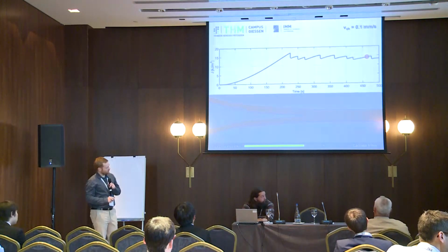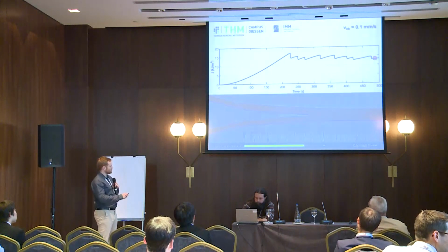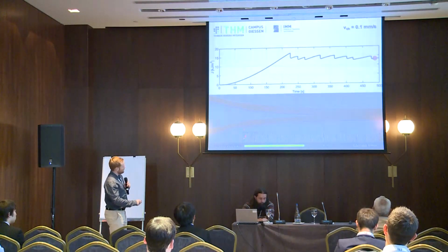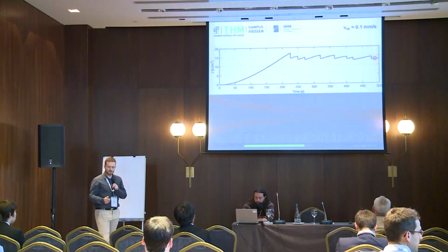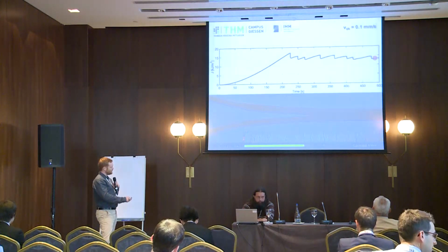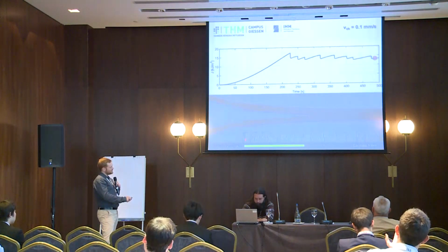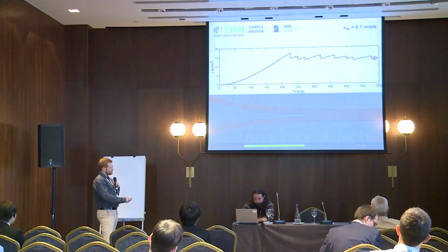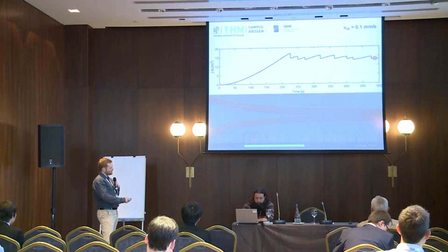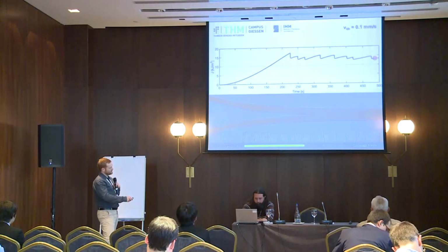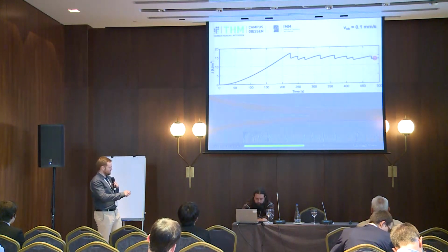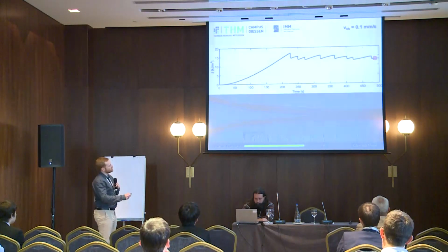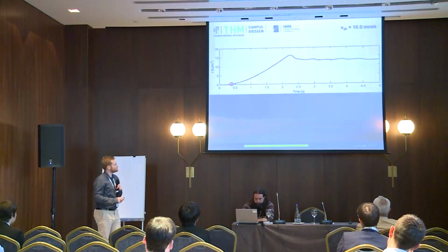So by the changing of the crack propagation rate, you see it in this curve here, but if we look at the fracture patterns, you see it in the fracture patterns as well. First, a flat region by inserting the razor blade. This is the first subcritical crack growth. And then you see a flatter region, which means that the crack jumps here. And then we have here a rougher region again, subcritical crack growth, and it jumps, and this is repeated here. So you see these rest lines here, or these are not rest lines, but these are areas of sub- and overcritical crack growing.